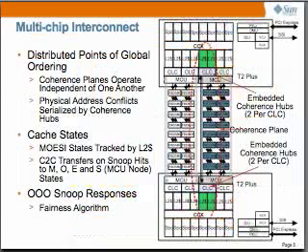This is for the techies. I just put it in for that. This is essentially saying the same thing. This is more detail on the cache coherence, and you can see what we call a coherence plane. Again, there are 4 of those. For those of you into cache coherence, it's maybe interesting to know that we have a MOSI protocol implemented there. And of course, we do cache-to-cache transfers, the C2C transfers.